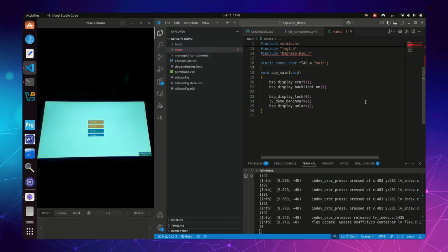rendered on the screen. And the DMA2D is a unit that accelerates the copy of 2D objects like images and between memory and peripheral. It's aimed to reduce the latency between the time that you send a draw buffer from a peripheral to memory or from memory to a peripheral.